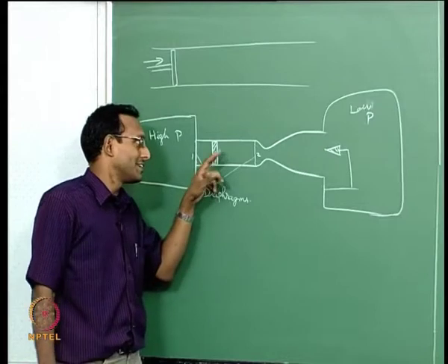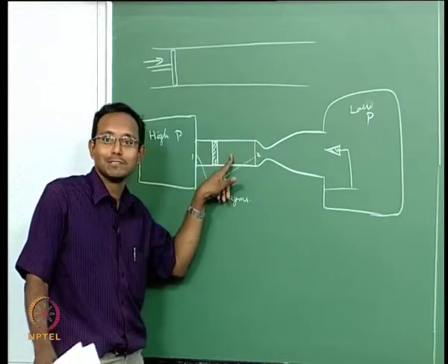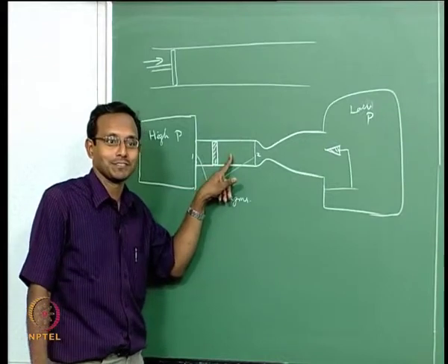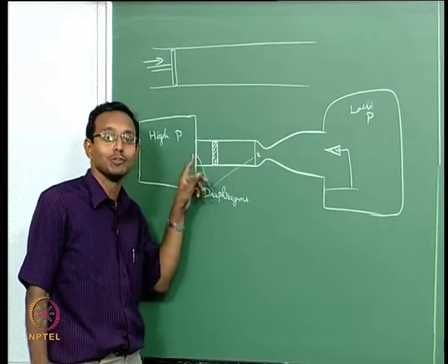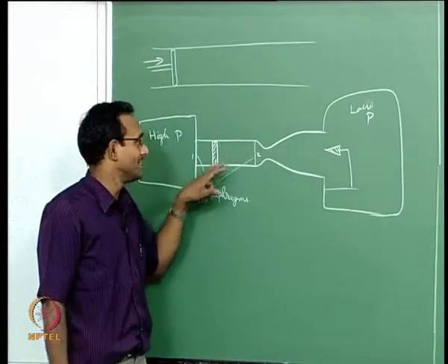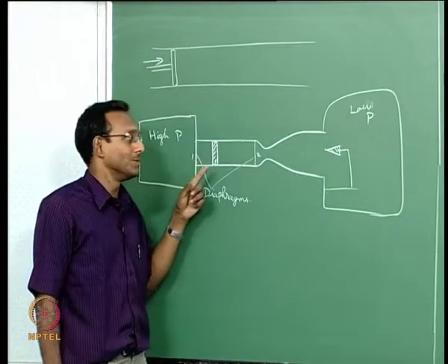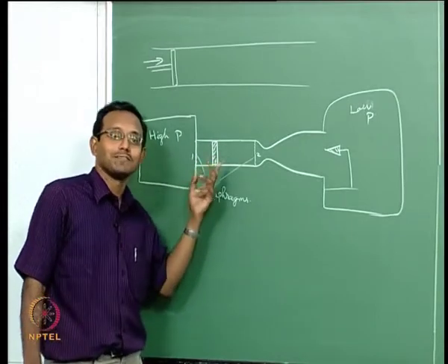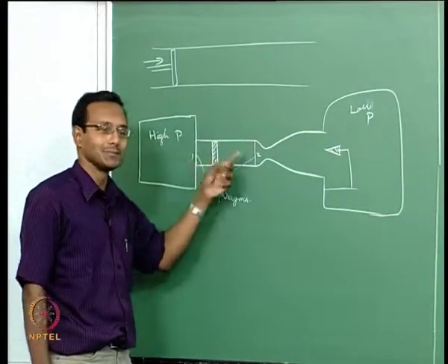Okay. Instead, I can fill only this region. This is nominally average pressure, probably close to atmospheric pressure. Storing that is easier, and I do not need to have huge volumes of gas. This is easier. That is one good thing about this tunnel. I can use special gases. If it is just air, I do not need all this. I will just use a shock tube, and a shock reflected tunnel is probably better than this.